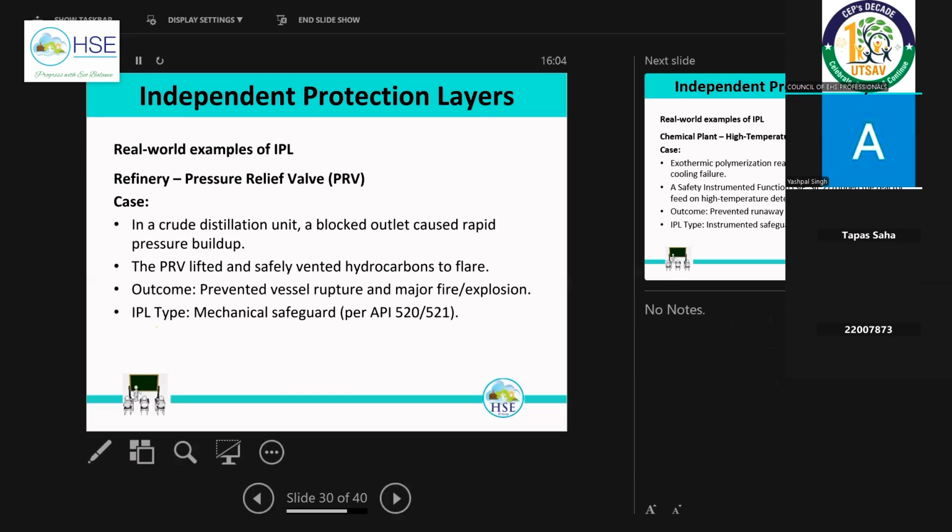Of course, response time is very important in all the cases, all the rules. So that is a basic for all the rules. That is rule 2, but applicable for all the rules, rule 1 to 9. So please consider response time in all the cases when designing the protection layers also. So these are the few basic rules for the protection layer.